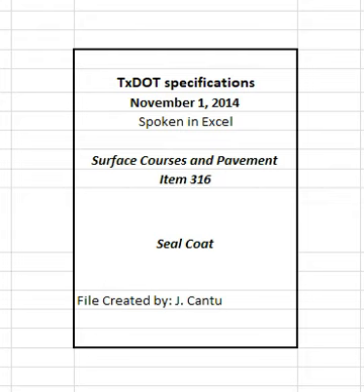3.3 Rollers. Unless otherwise shown on the plans, furnish light pneumatic tire rollers in accordance with Item 210, rolling. 3.4 Broom. Furnish rotary, self-propelled brooms. 3.5 Asphalt storage and handling equipment. When the plans or the engineer allows storage tanks, furnish a thermometer in each tank to indicate the asphalt temperature continuously. Keep equipment clean and free of leaks. Keep asphalt material free of contamination.